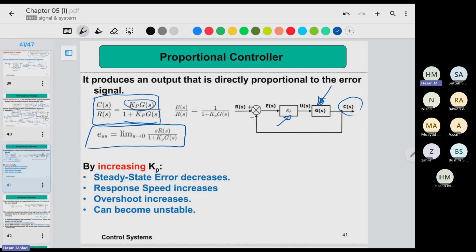So this is kind of the gain. You push more pressure, it might follow the output more closely to what you want, right? This is the simplest thing that you can do. So here is the effect of this KP. We call this KP the proportional controller. Proportional is just a constant factor to the input. We call it the proportional factor.